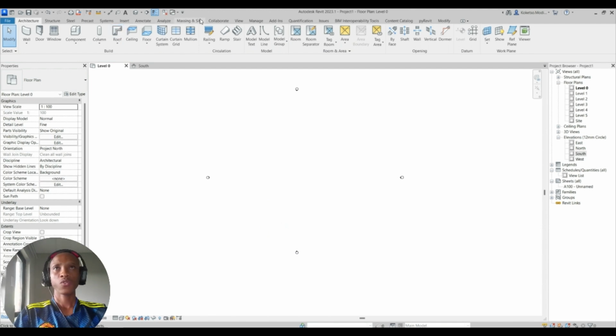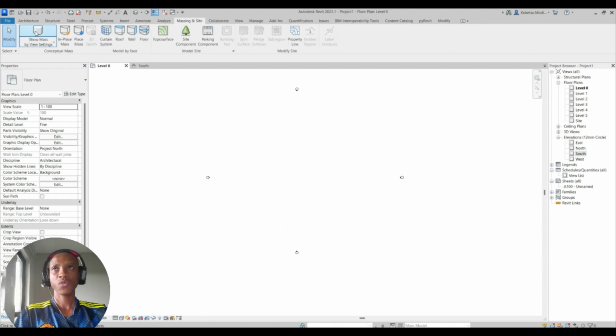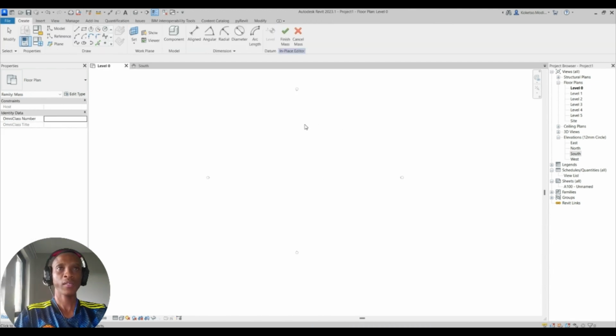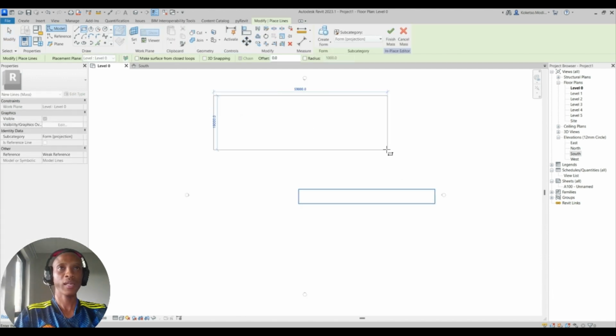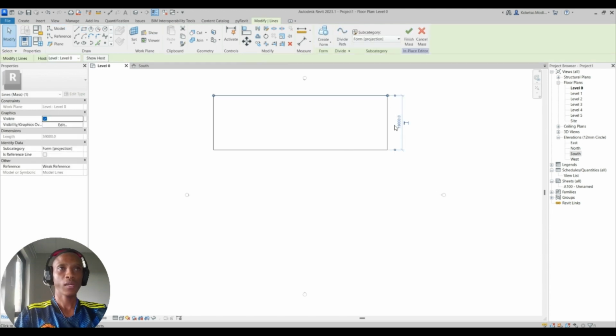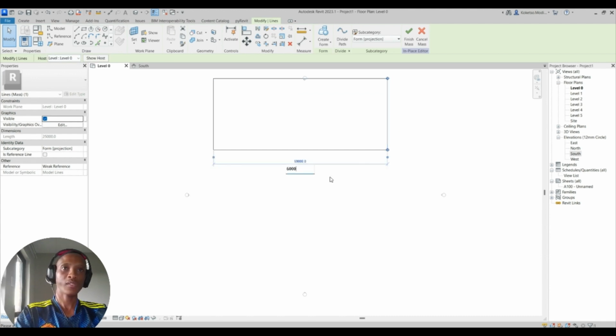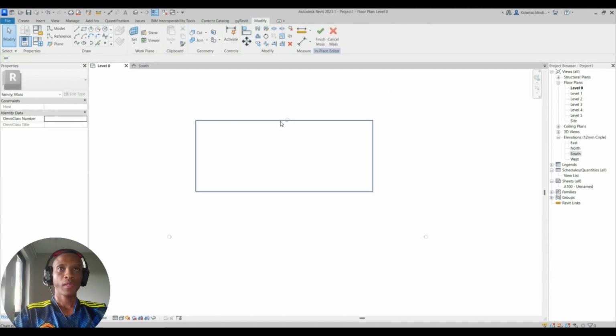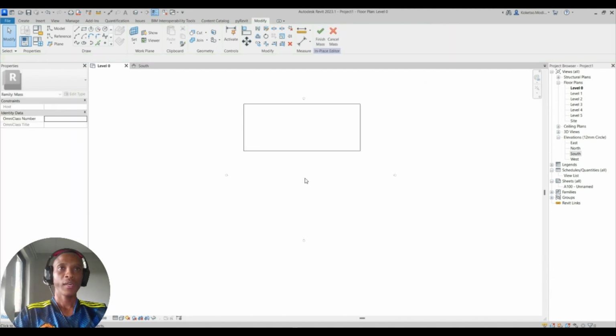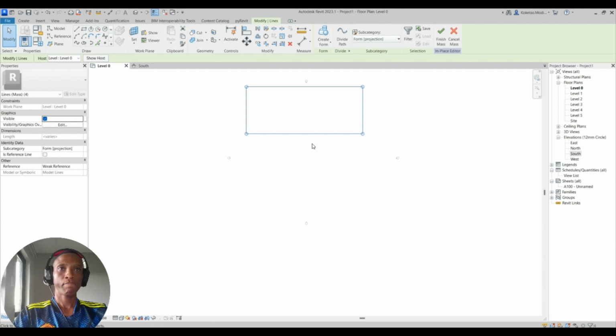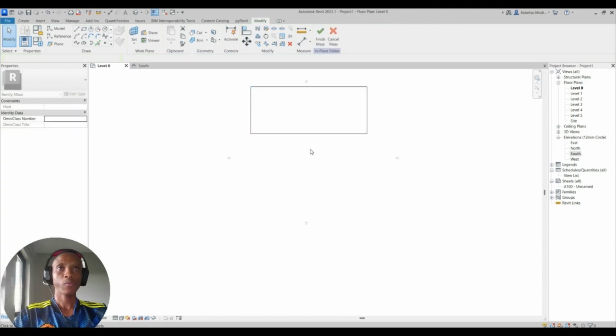And the next thing, I'm gonna go to massing inside. I'm just gonna check this show mass and say in place mass. So this is a conceptual design, and we're just gonna use massings and place some floors. I'm gonna start with my rectangle, place it like that. And this rectangle, let's make it 25,000 by 60,000. I'm just gonna nudge it in, and yeah, I'm gonna leave it like that.